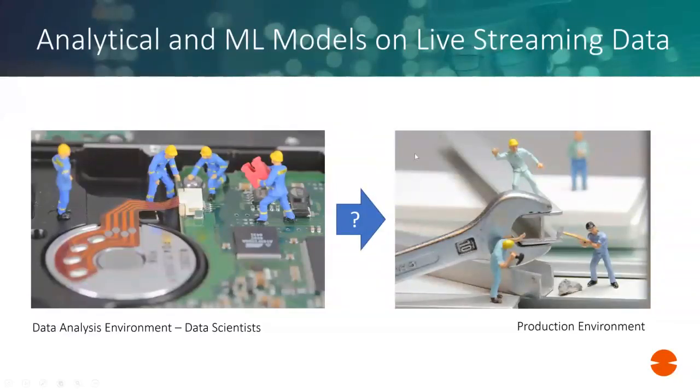In the production environment, you may have fouling or influences caused by seasonal changes. For example, in a refinery, you may have a summer grade and a winter grade of diesel that you're producing, which provides you with a different set of data inputs and different variation in the data inputs, and you need to take that into account.